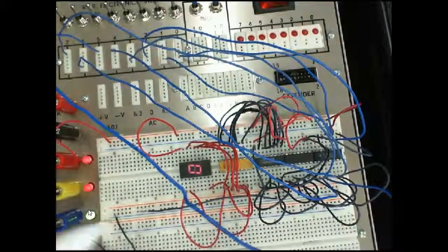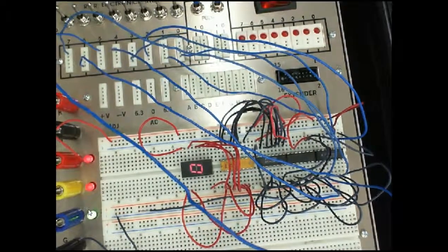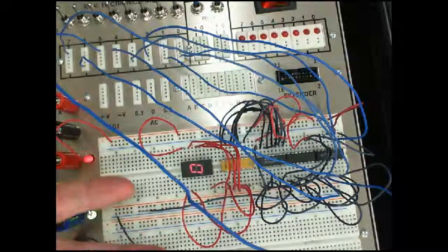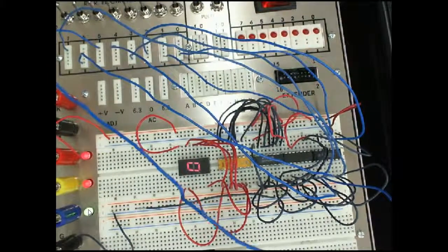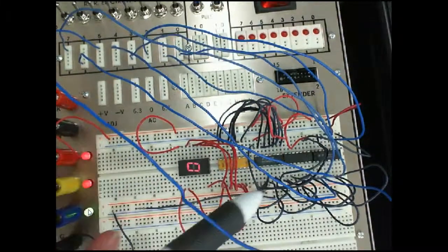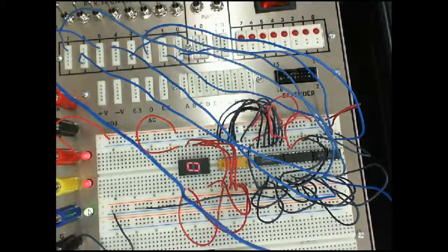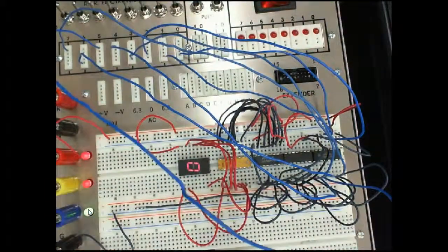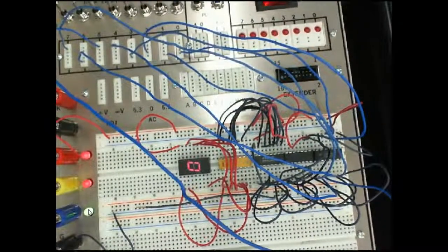So it seems like we have a lot of wires to connect this circuit up. But if we had to connect this up using bipolar transistors, guys, that would probably be 20 times more wire than we have connected there, even more. And not only that, for every inverter right here, that is 5 transistors just to do one inverter. I'm using 4 inverters. So 5 transistors and all the wires and all the resistors to connect those together. If you think about the number of components and the amount of wiring that would be required to replace this one IC, this is nothing.